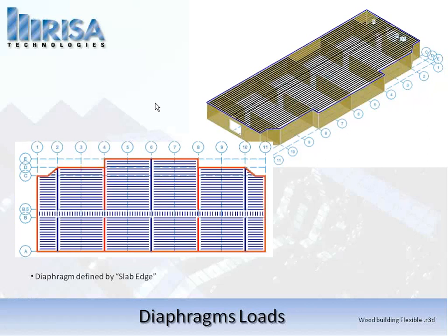That's the diaphragm edge. And what you've got here, if we look at the lateral walls or the lateral system, are what's resisting the lateral loads. Whatever is in red in our model is defined based on that lateral system. You can call a wall a lateral system, you can call a beam a lateral system, or a column. And typically in wood, we're going to be setting everything to be walls, to be lateral. But they're going to be resisting the lateral forces.